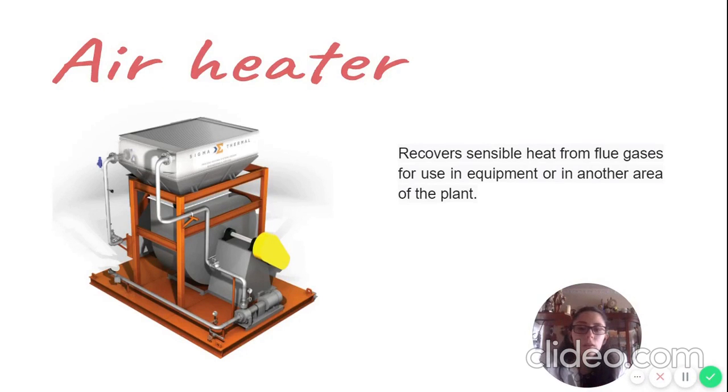First, heat losses in combustion gases are reduced, saving approximately 1% for every 20 degrees Celsius reduction in the temperature of these gases. It increases the flame temperatures in the combustion zones and increases the heat transfer. Second, combustion is produced with less excess air, and some fuels can only be burned with air preheating, such as coal.